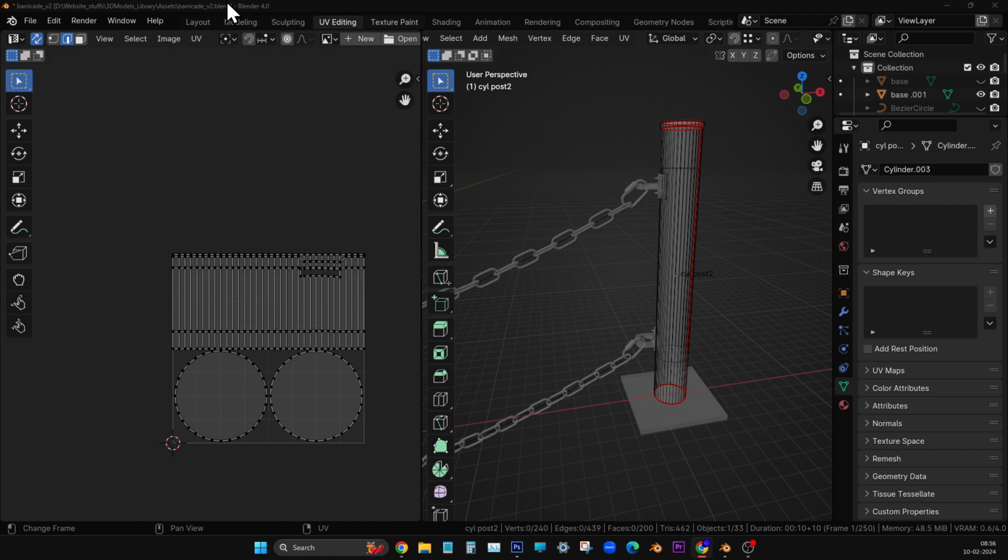Yeah, just see the view. Turn your camera and then now you do. Only one is it. Oh, right. Okay, right. Deselect and then go to edge mode. Yeah, you can select the loop and then scale it down in Z axis.